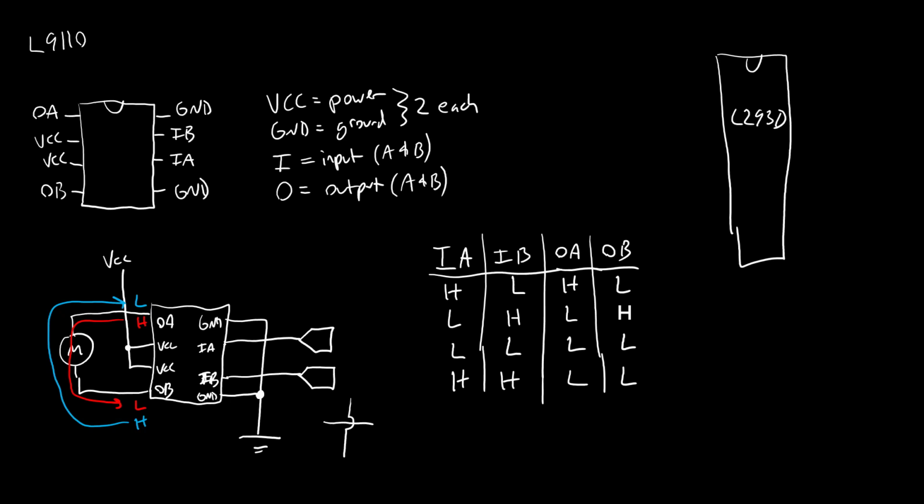We haven't really talked about this yet, but you could use something called a PWM signal to modulate the speed of a motor on these pins, where if you send in 0 to one pin, and then rather than having the other pin high the entire time, you turn it on and off very rapidly. You can then use that to control the speed of the motor. On the L293D, it has 2 direction pins that you only set high or low, and then a 3rd pin intended for use with this PWM signal. So again, it's going to be specific to the H-bridge. These are just 2 popular ones that I have experience using.